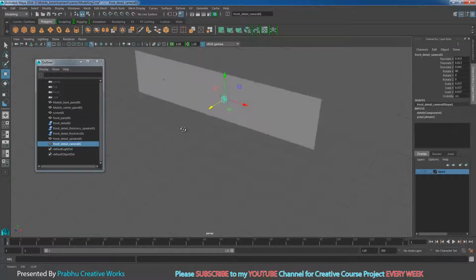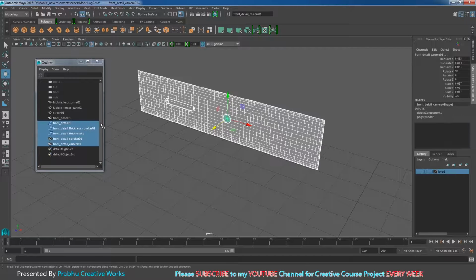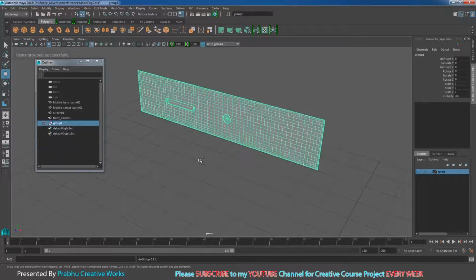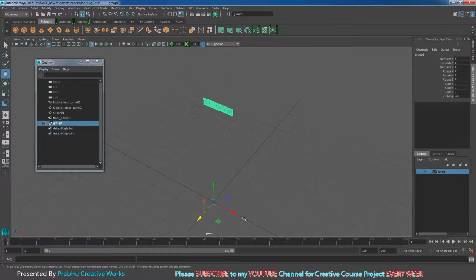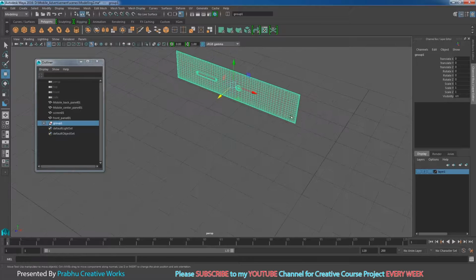So like this. So now we want to select all these objects over here and press Ctrl G on the keyboard. So that means your objects will be grouped. So see here, our pivot will be changed to here. So go to modify and choose center pivot. So our pivot will be changed.